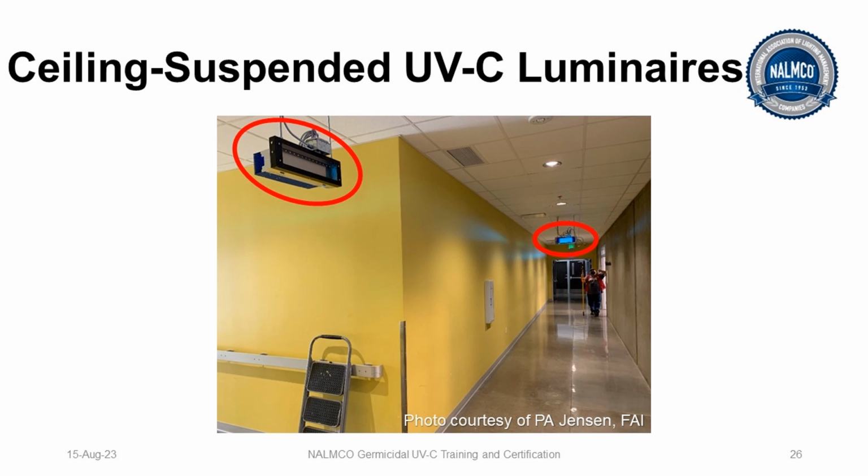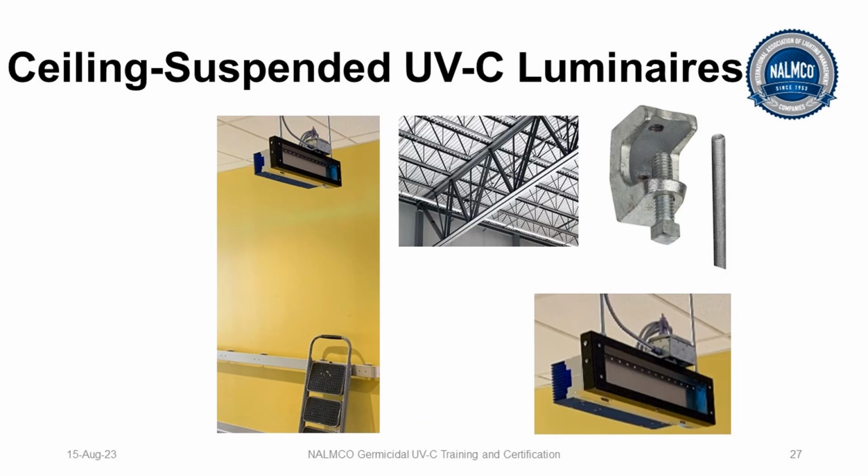Here you have ceiling suspended UVC luminaires. If we take a look here, there's a 3/8 inch rod from this bracket all the way up to the high space above the drop ceiling, using standard clips. So it's relatively easy to do, but you'd need a professional to do it and do it right.